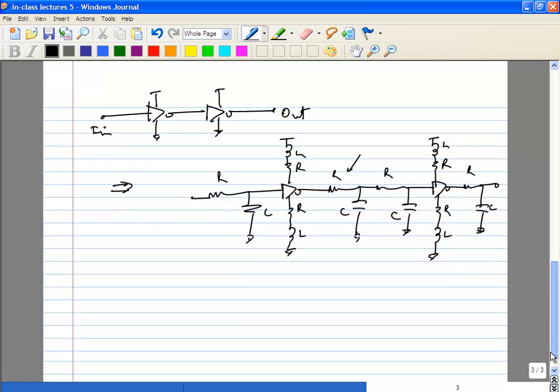And obviously this is a very important step, because LPE is typically where you will find out issues with your layout. So design the circuit, layout, LPE, simulate, and then you will see degradation. You will go back, modify the layout, so you can find out where the layout gets spoiled, where the design is most sensitive to layout.